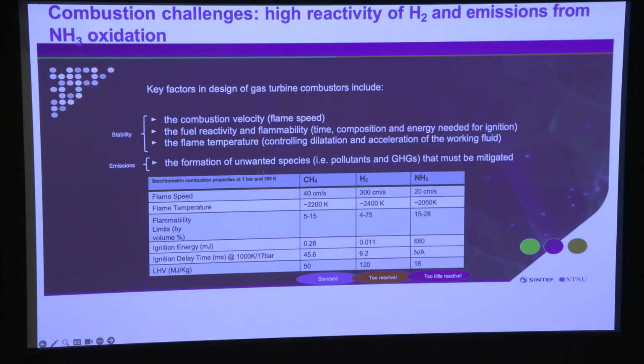And hydrogen, because of its fast burning rates, 300 centimeters per second, I think this is for stoichiometric hydrogen, is a real challenge to use in gas turbines because it can flash back, meaning near the injector, it can actually propagate upstream and destroy or damage hardware in the gas turbine. It also has high temperature and high heat release rate, which can couple with the acoustics in your engine and create thermoacoustic dynamic problems as well.